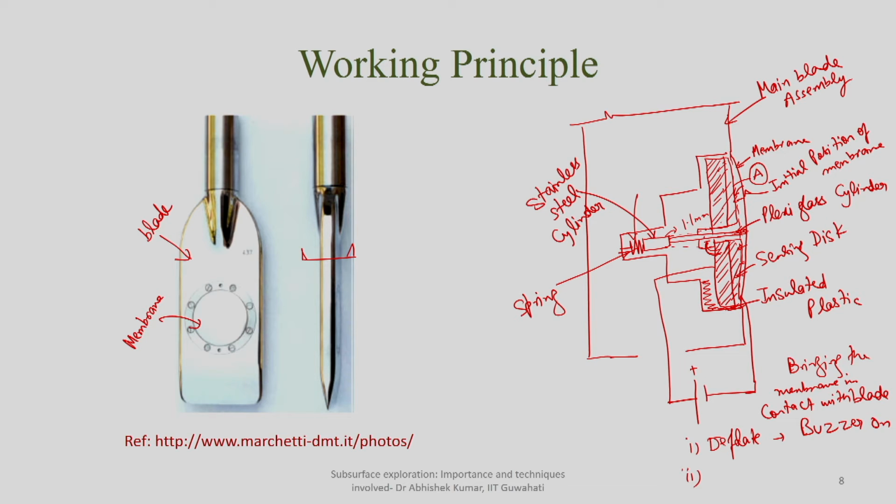So again for 1.1 mm, that is inflation or movement by 1.1 mm. Initially you applied some suction pressure, because of which it inflated, and because of this inflation the membrane comes in contact with the sensing disc. The circuit was complete and the buzzer sound was on.